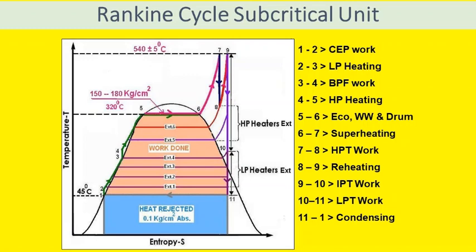So it is the CEP work, and 2 to 3 it is part of low pressure regenerative feedwater heating with steam extracted from LP turbines and MP turbine. So LP heating is there between 2 to 3, which is adding up heat in the condensate.